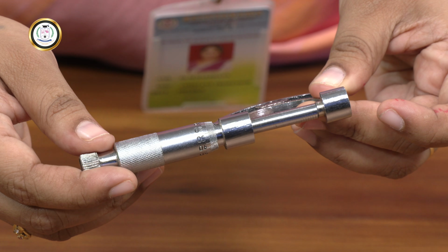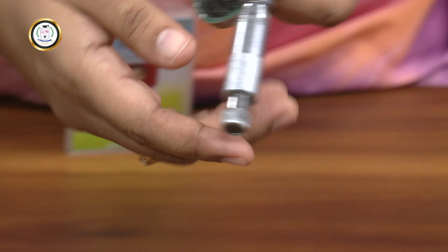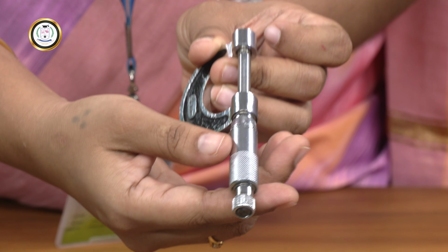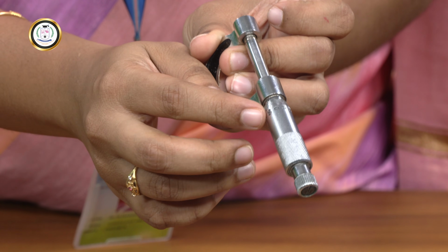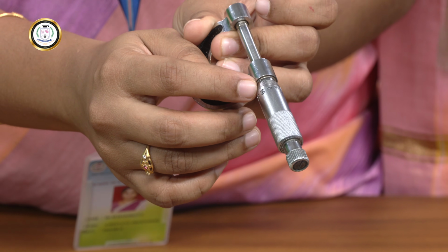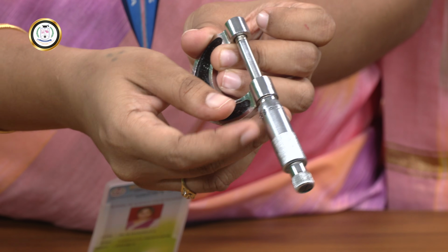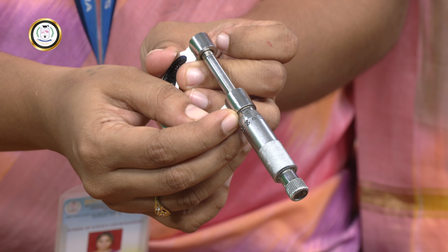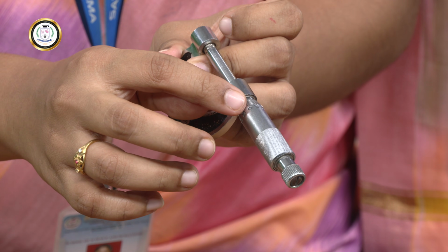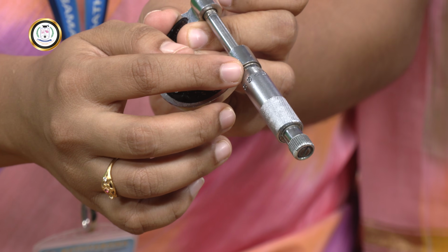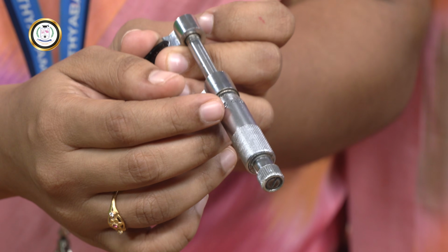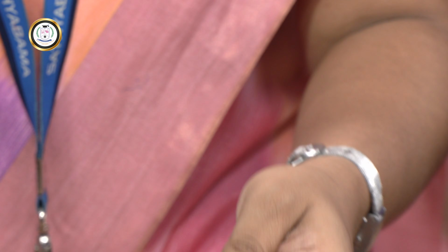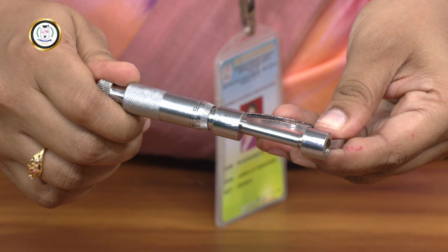Instead, if your pitch scale 0 coincides, as I showed you in the PPT, if the head scale 0 coincides like 10, this is called a positive error, and if it is below the head scale 0, then it is a negative error. Now in this instrument it is coinciding with 90, which means it carries a negative error of minus 10. So from 0, below the 0, it is coinciding at the 10th division, which is 90. So the value of the error is minus 10. So now we have calculated the error for this instrument.